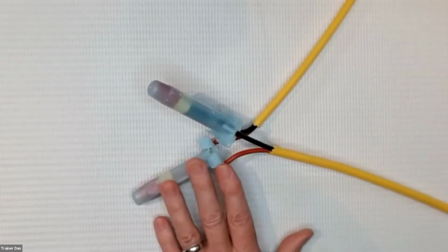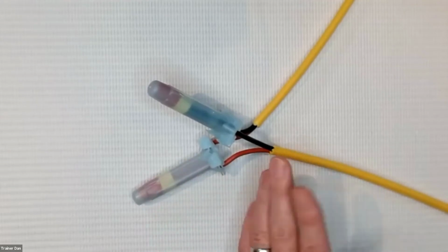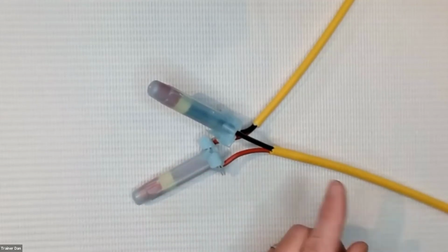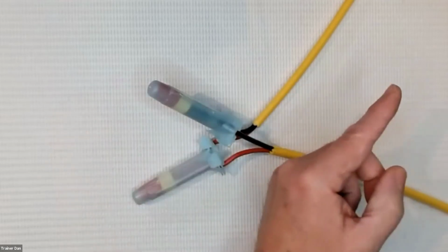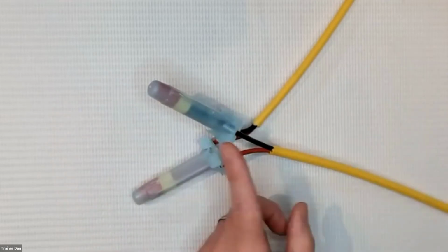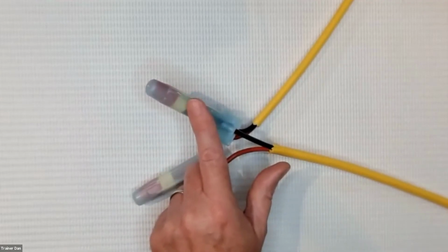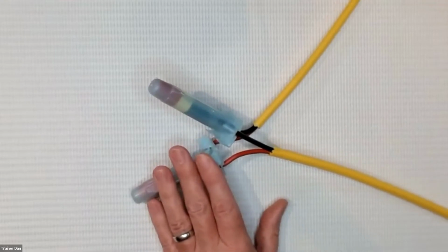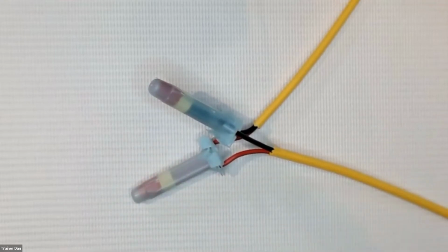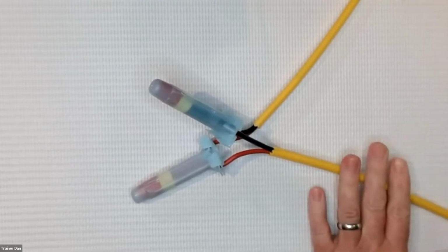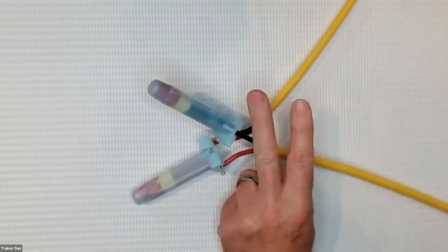It may create communication problems with the device, because we've got that patented two-way digital communication where we send out some information and then get a packet of data back, and it has to communicate back and forth. Any corrosion on this, or not using the correct splice, is going to corrupt that data, and we're not going to get good data back. That's a good reminder, Dan, that voltage can travel through corrosion and communication travels through corrosion. Yeah, and this is a drum that I beat all the time: a two-wire path is both a data path and a power path.